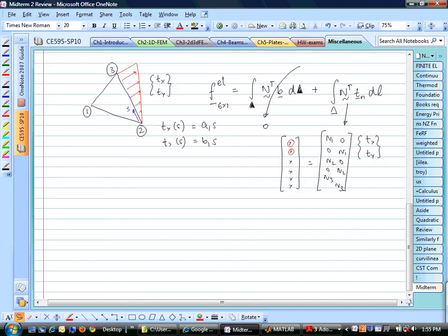Essentially, even on the exam, you should try to eliminate as many terms as possible beforehand. In the last midterm, I gave you a 3 cross 3 3-noded linear line element, but one column and one row you could have eliminated just by the boundary conditions. So you needed to integrate only a 2 cross 2 matrix.